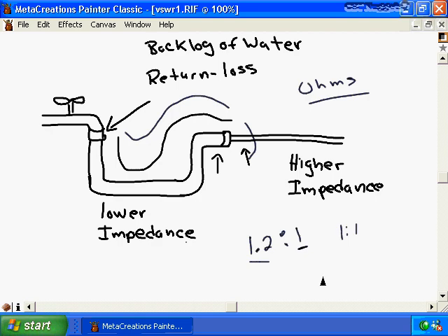Now, speaking of antennas, there's a few key things we need to know about antennas. Now, we've got an entire video devoted to different types of antennas, but here we're going to learn about some of the principles of antennas. An antenna is used to either transmit or receive a radio frequency wave. Now, when it's transmitting, it's going to convert electrical energy into a radio frequency wave. When it's receiving, it's going to take this radio frequency wave and convert that into electrical energy. Also, the shape and size of the antenna is directly related to the frequency at which the radio waves can be transmitted or received by an antenna.